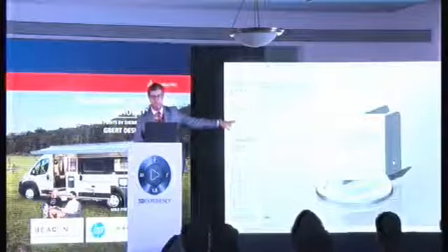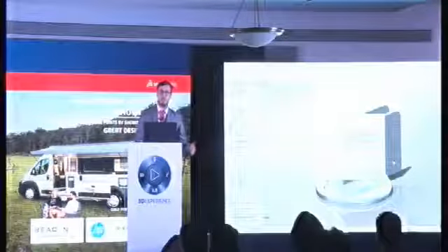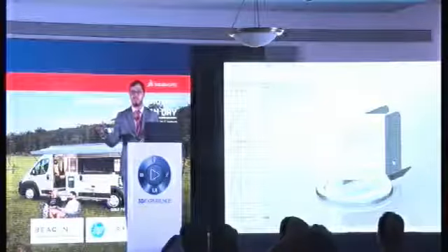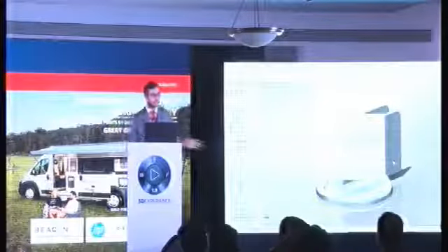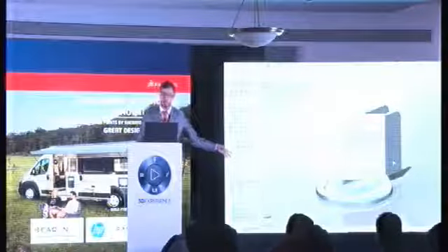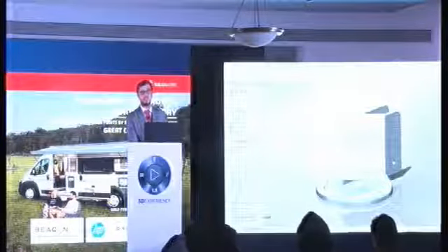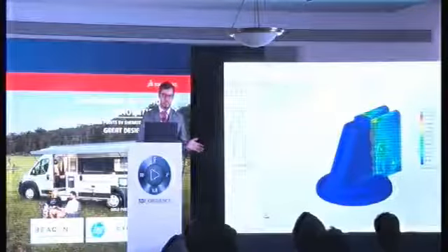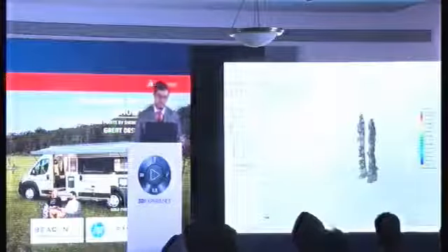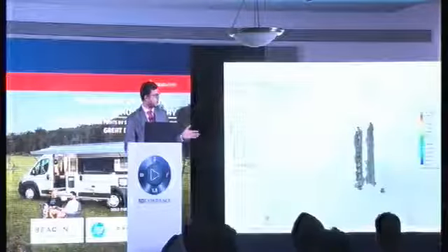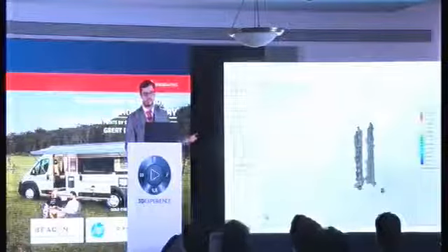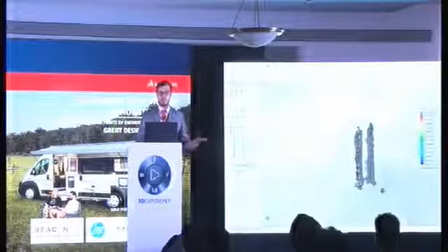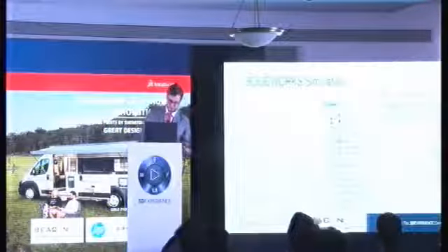So as you can see that it has detected stress singularity. Stress singularity means that whenever you reduce the mesh size, your stress will keep on increasing. So that is a divergence. As you can see that the plot shows such kind of a divergence. So you can now confirm the stress singularity directly inside the same window. So let me just isolate the stress singularity areas. As you can see that the sharp corners with no fillets, the stress singularity is over there. So I can go ahead and create fillets and improve the life of the model as well.